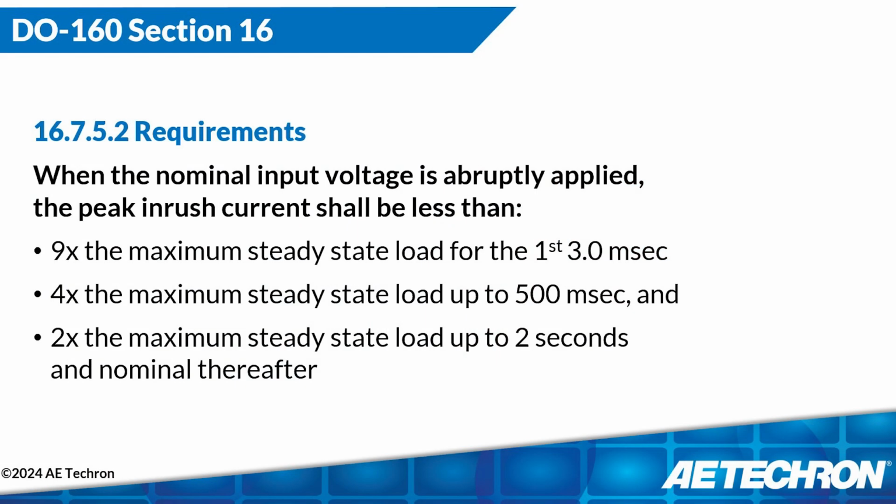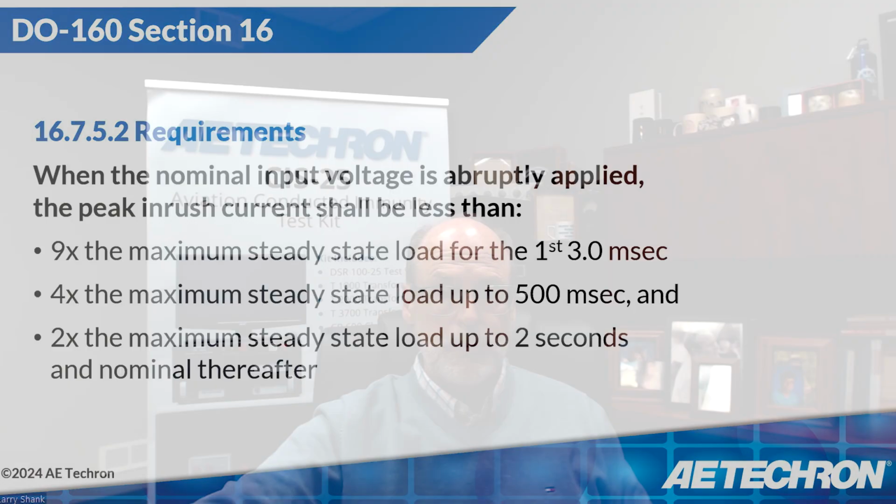16.7.5.2 inrush current requirements, there is a test that requires the test lab to verify maximum inrush currents of the DUT. And these are 9 times steady state at 3 milliseconds, 4 times steady state at 500 milliseconds, and 2 times steady state at 2 seconds.